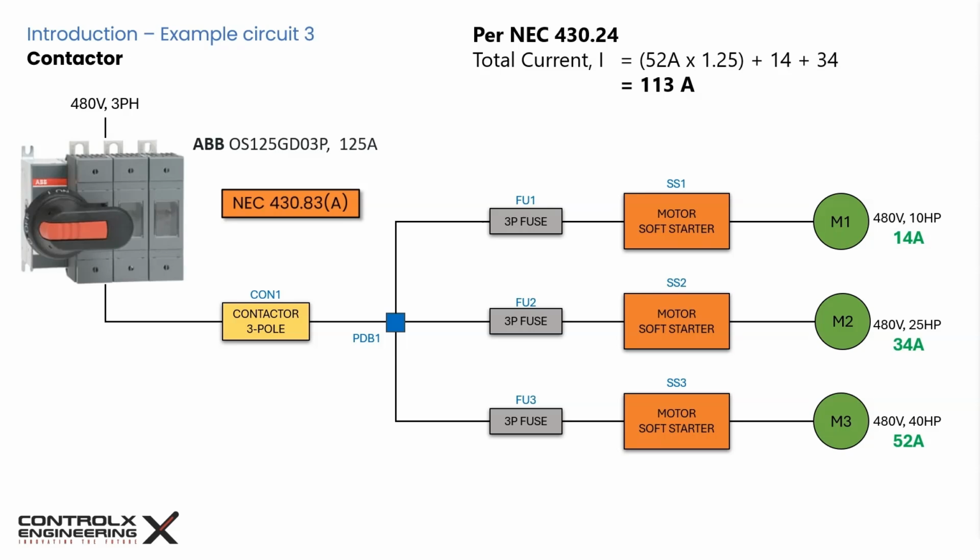So in our case, we need a three-phase contactor rated for use in 480 volts or higher voltage systems. The contactor also must meet the appropriate utilization category for the load type. For motor loads, the category is typically AC-3, which is designed for starting and stopping squirrel cage induction motors under normal operating conditions. Another consideration is that the contactor must be able to withstand short circuit conditions without damage when used in conjunction with the specified short circuit protection devices like fuses or circuit breakers.